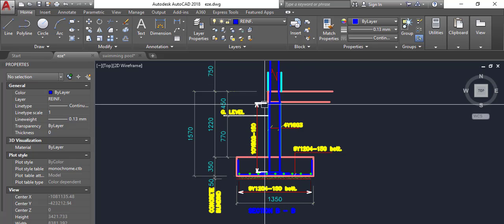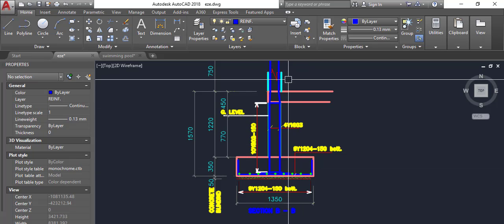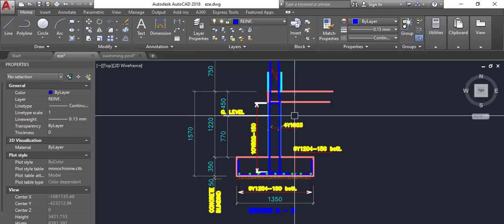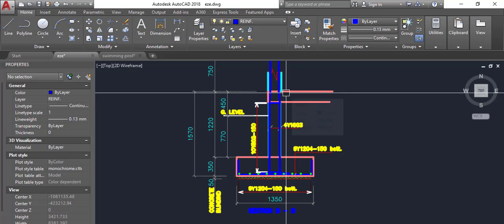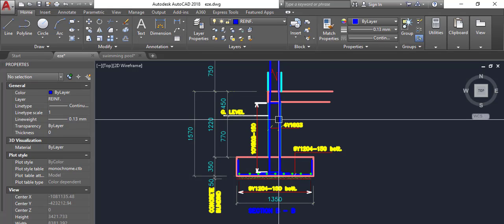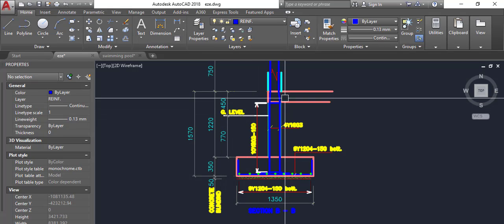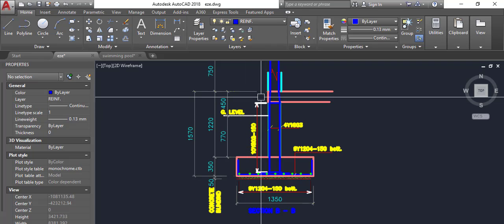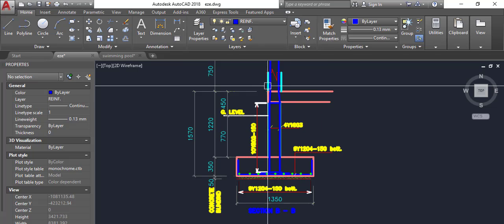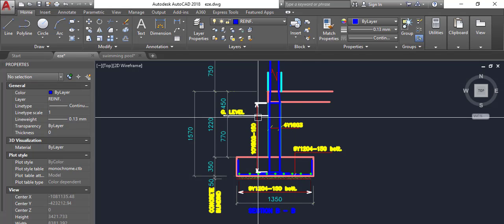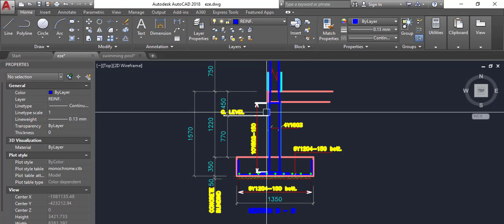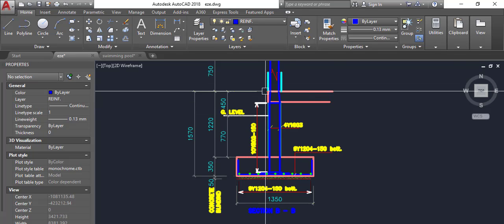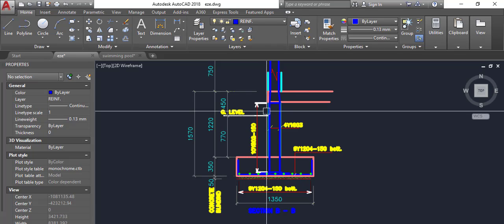But whatever you do, of the depth of your beam, at least 450 must be out of the ground, depending on the area you are working on. Some may be higher, up to 600 mm above the ground, but the minimum should be 450 above the ground.